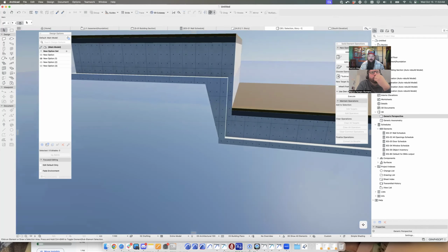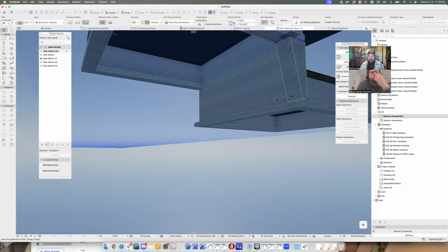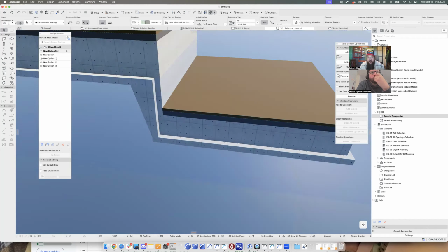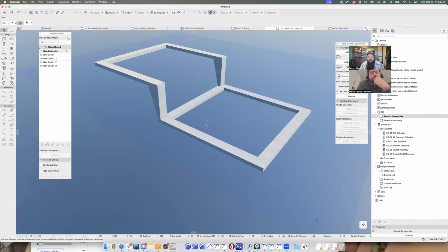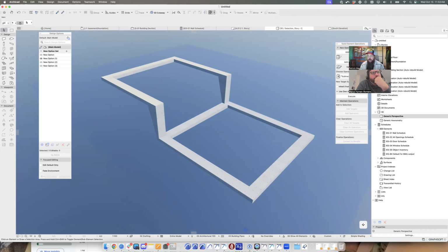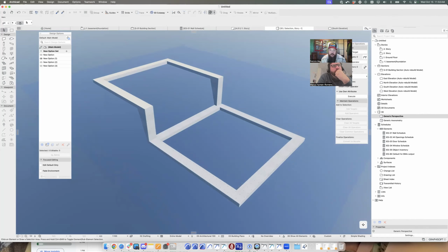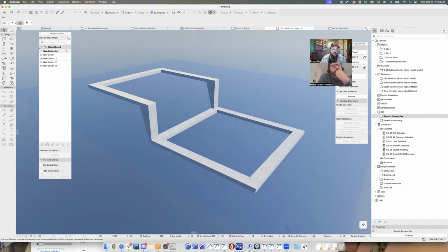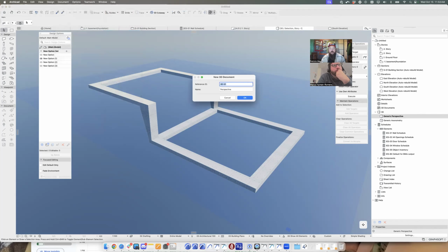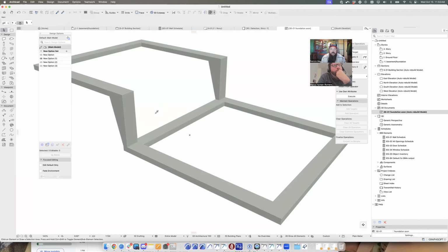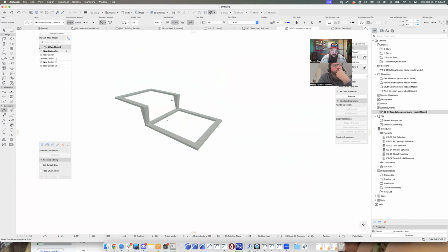But for any foundation axon, this is going to get me the foundation axon that you're going to need to see on the job site to understand where those footing steps need to work with the site, right? So here, if this is part of my documentation, I could take all of my footings and go to document, document tools, 3D document, foundation axon, and then I can even annotate and dimension directly into here.